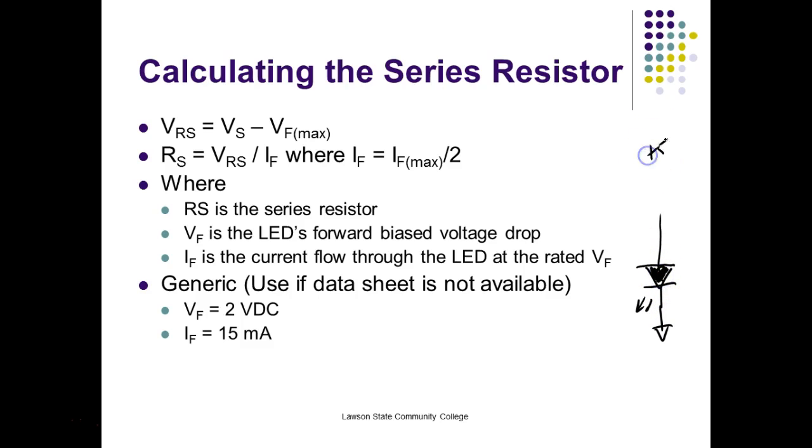And I'm going to power it up over 5 volts. So if I put this thing across 5 volts, if I apply that 5 volts right there, what's going to happen? It's going to burn up before you even look at it because it's over the VF, right? You understand that? Anything over VF is considered a short circuit.